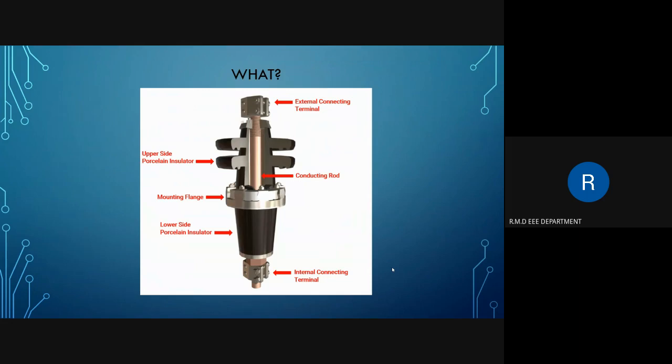Now, in the case of bushing, all materials carrying an electric charge generate an electric field. When an energized conductor is near a material at earth potential, it can form very high electric field strength, especially where the field lines are forced to curve sharply around the earth material. So the bushing controls the shape and strength of the field and reduces the electrical stress in the insulating material.